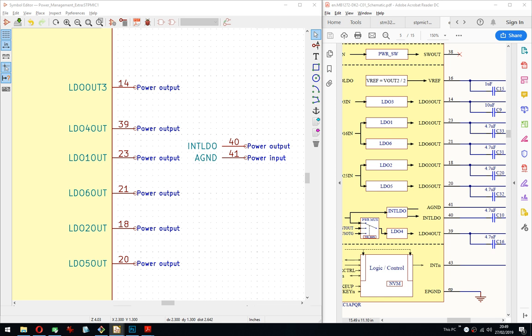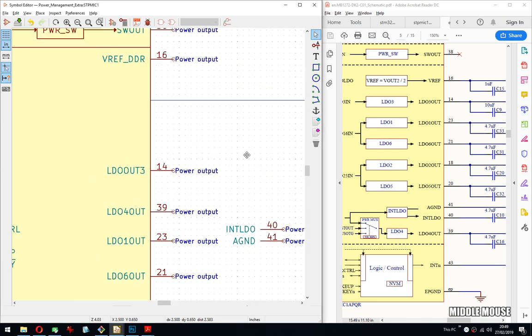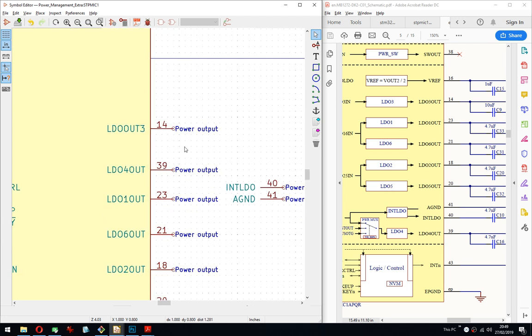And yeah, I really wanted to have a galvanically isolated CAN bus because I don't want my laptop to explode when I plug things wrong. That's just not a good idea. And with this I have full galvanic isolation, I have ESD protection, I have native Linux socket CAN support.